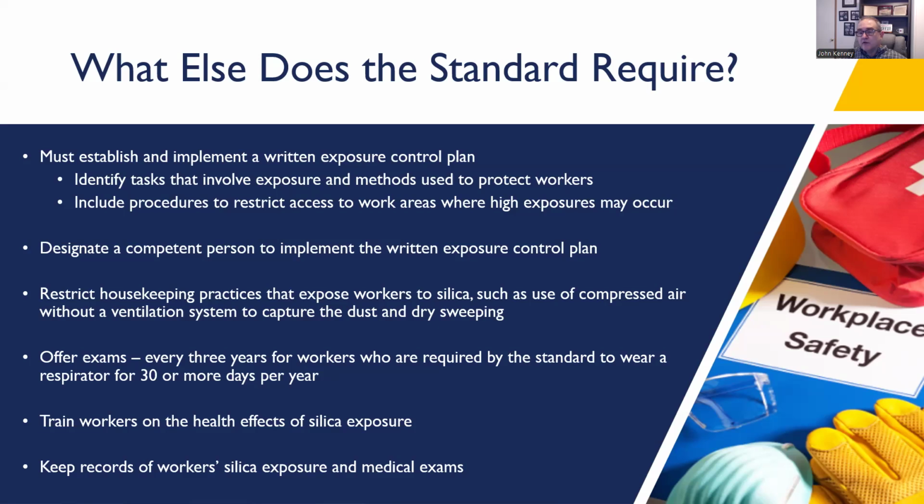But again, check with what the current regulations are in your area because we have state OSHAs as well as federal OSHA guidelines. Train your workers on health effects of silica exposures. Again, just like we do in everything else, they must be trained and documented. Keep records of workers' silica exposure and medical exams.